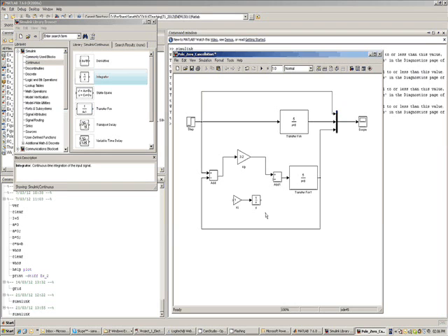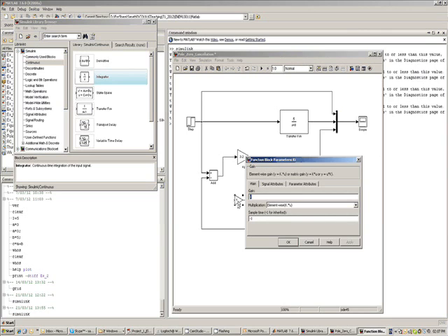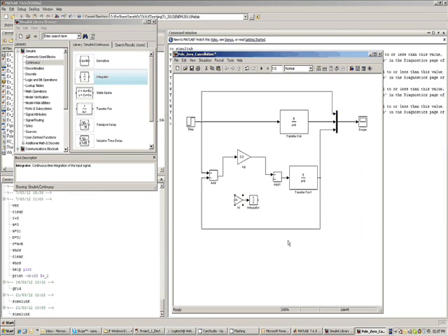So instead of integrator, you also can rename it as S. That's not important. Let's not do that. I'll go back. Let it be integrator. And your Ki value is how much? It's 25.6. Apply, close. Then you feed the error to that, like this.